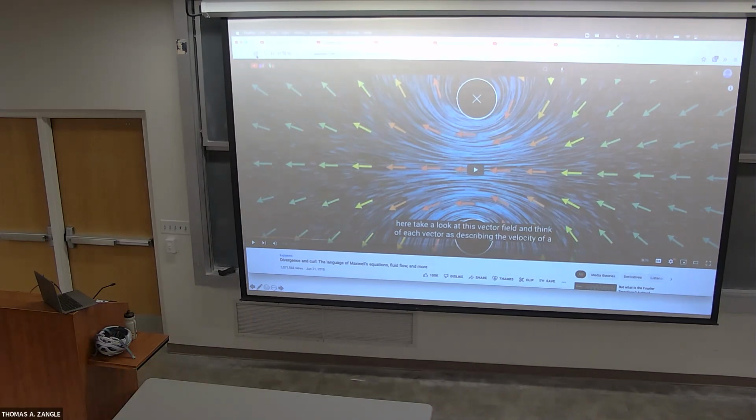So the fluid is traveling faster out of this control volume in the x direction than it entered. Del dot v equals 0 implies that there's more material moving out of here in the x direction than came in. That material has to come from someplace. And we would see that it could, for example, come from 2-dimensional flow, deceleration into it.